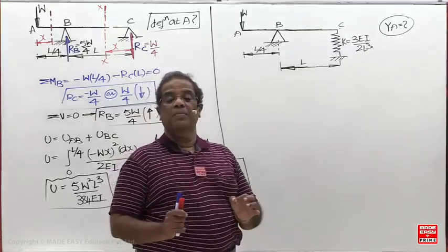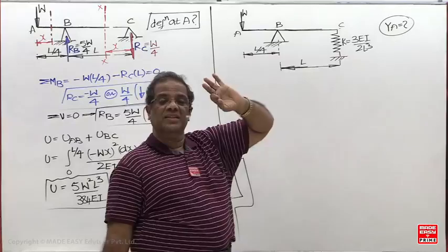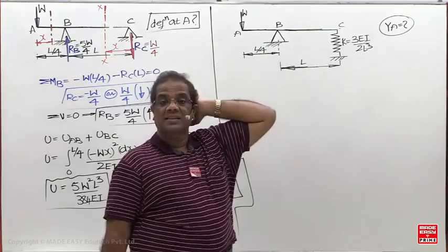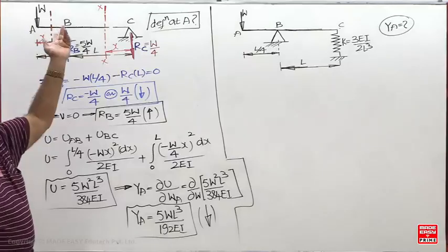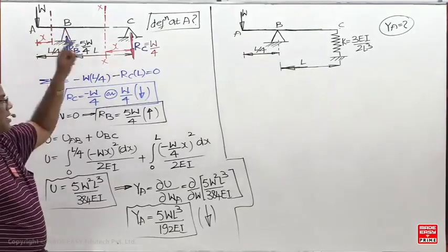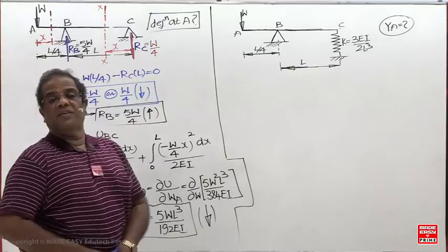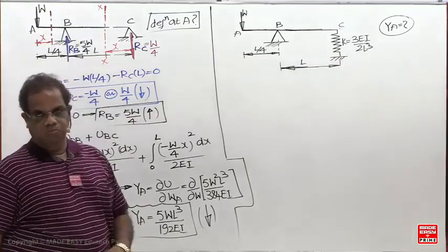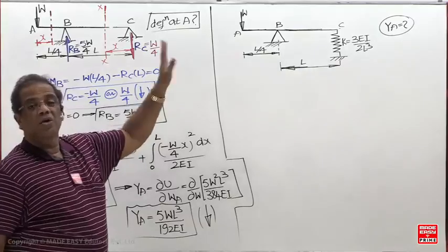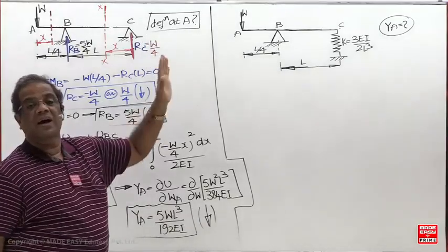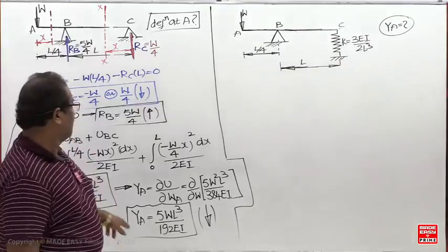So whenever a beam is supported by flexible supports, to find out the deflection, always strain energy is required now. That is, the Castigliano theorem is required. This question can also be done with the Macaulay method, any other method now. But here, whenever a flexible support is given, you have to go for the Castigliano theorem. No other method is valid. Only the Castigliano theorem is required. So what change you have to make now?